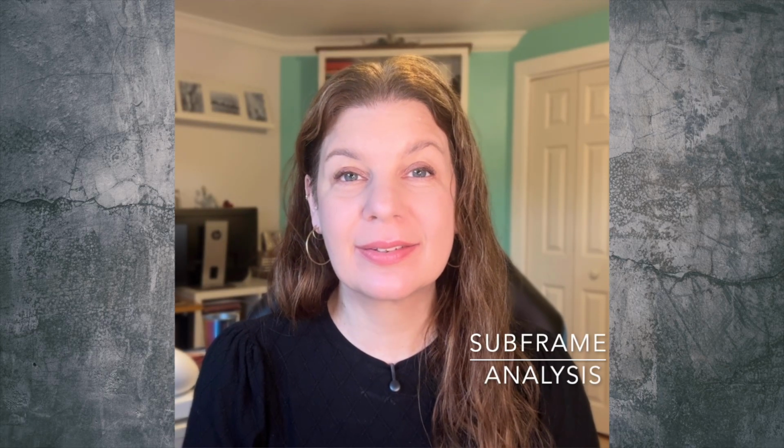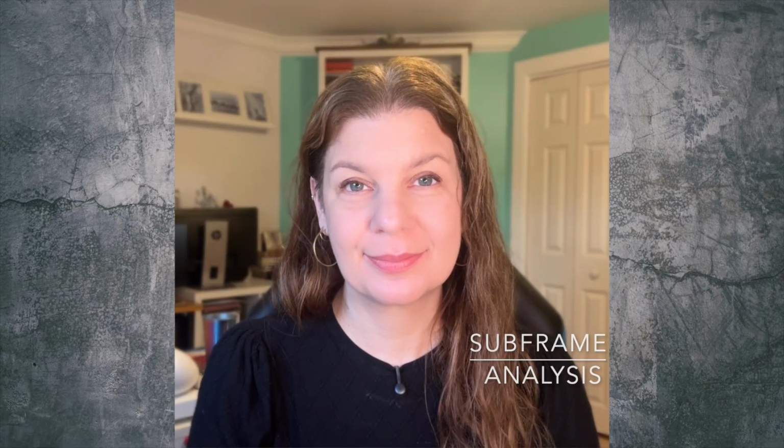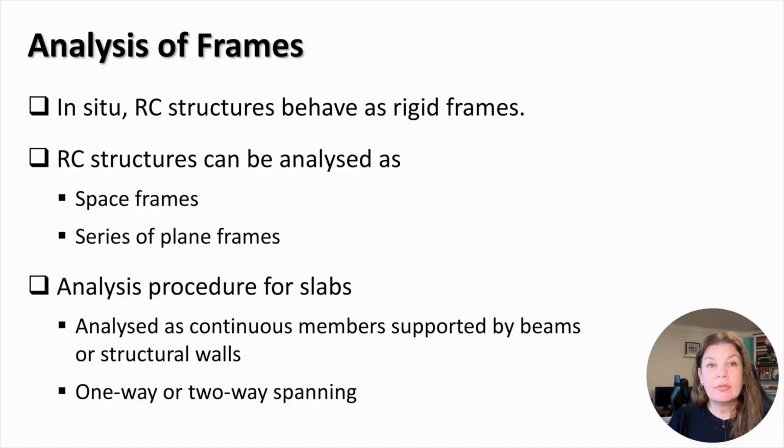Today we'll be discussing subframe analysis. Reinforced concrete structures behave as rigid frames. Therefore, they can be analysed as space frames or a series of plane frames. Slabs are analysed as continuous members supported by beams or structural walls. Depending on the ratio between the side lengths, slabs can be considered as working in one way or two ways.